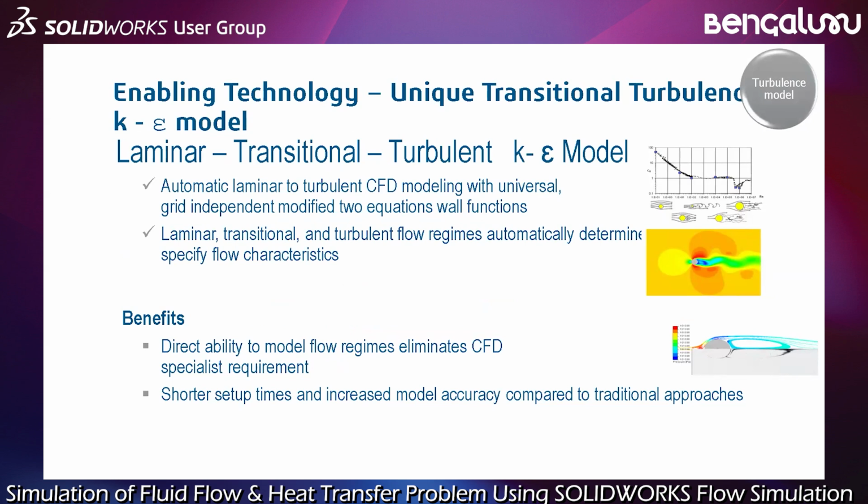For the turbulence model, the user doesn't need to select which model. The Flow Simulation product has one turbulence model adapted to the technology. Okay, so first it is automatically set, and you don't need to have a specific mesh for this, compared to some other tools where you need to have the boundary layer meshed accurately to get accuracy with turbulence. Okay.